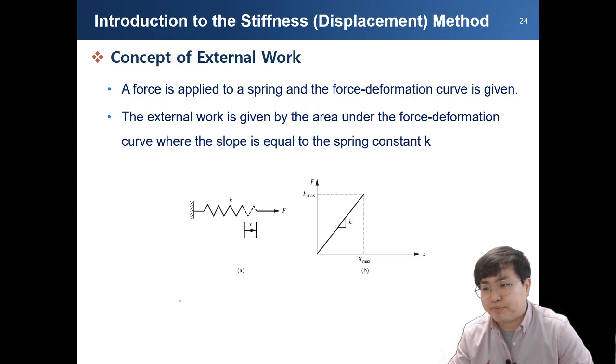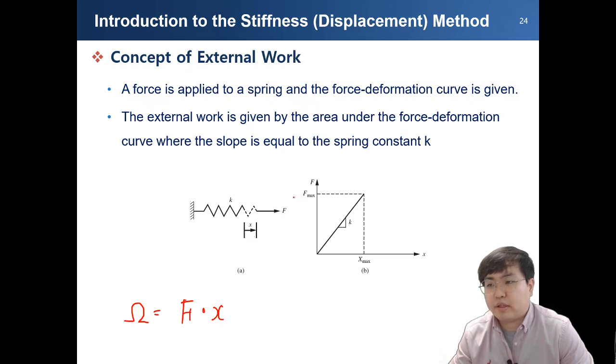Let's think about what the external force is. We apply force F, and this structure will deform by this length. This is the external force, the potential energy by external work. And then let's think about the internal energy U.